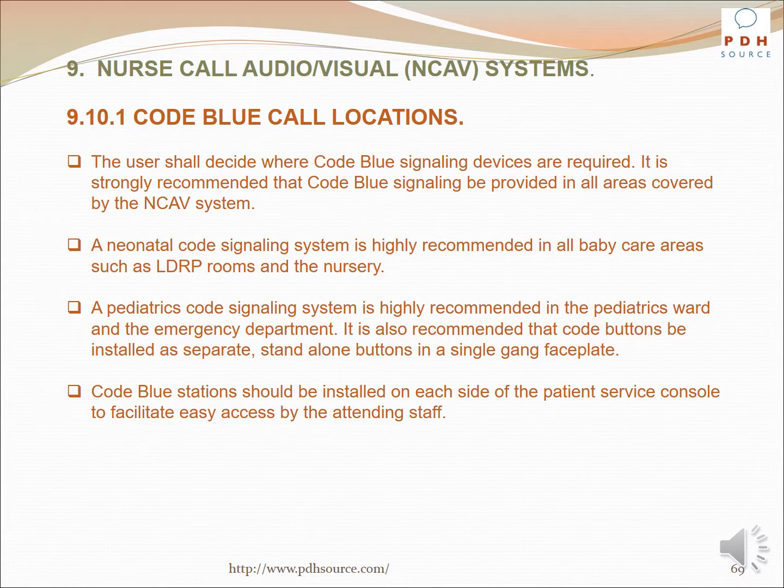A neonatal code signaling system is highly recommended in all baby care areas such as LDRP rooms and the nursery. A pediatrics code signaling system is highly recommended in the pediatrics ward and the emergency department. It is also recommended that code buttons be installed as separate standalone buttons in a single gang faceplate. Code Blue stations should be installed on each side of the patient service console to facilitate easy access by the attending staff.